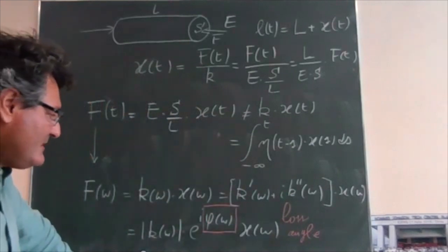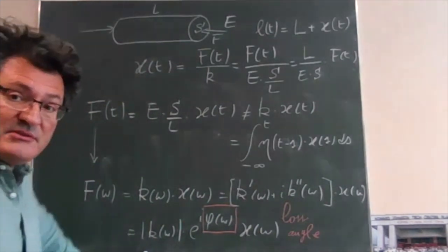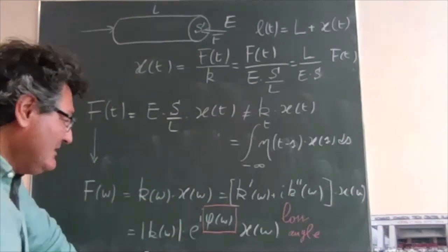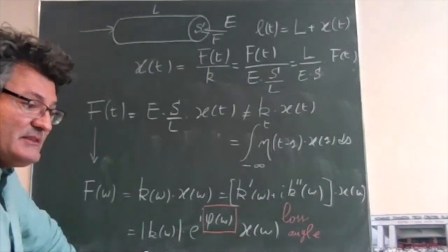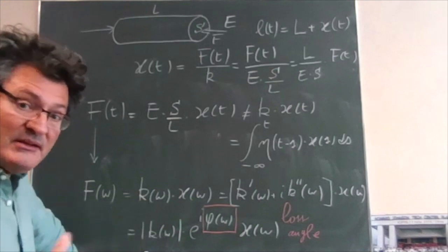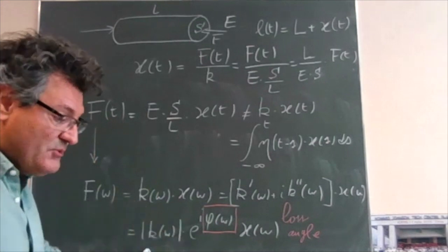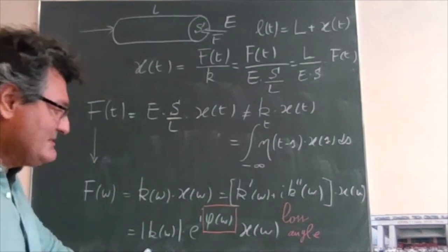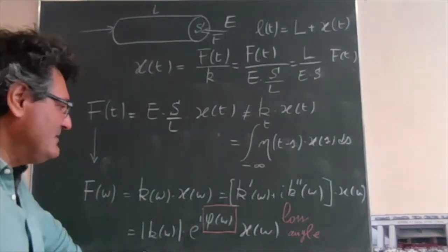Because when this angle is not zero, the external force produces a work that is negative after each cycle. So practically, the external work is dissipated inside the material. In practical terms, at every cycle, some work done by the external force is transformed into heat that is heating up the material. Okay, it's a tiny fraction, but that's what is happening.